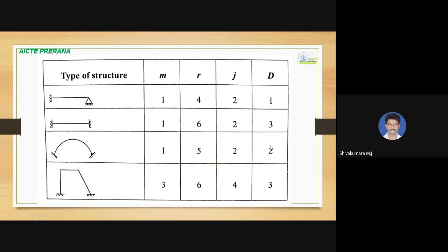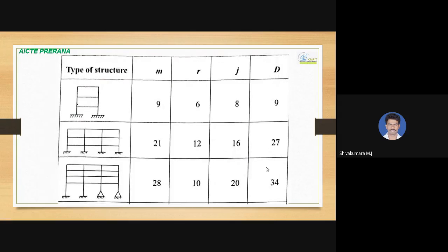So very simple, and multiple floors and one frame you consider here. So totally 4 columns are there and beams are running through 1, 2, 3, 4. 4 supports, all are fixed support. So that means each support offer 3 reactions. So 3 into 4 number of fixed support, it is 12 number of reactions. And then number of members, it is 1, 2, 3. So 3 number of members, 3 segments, totally 9.